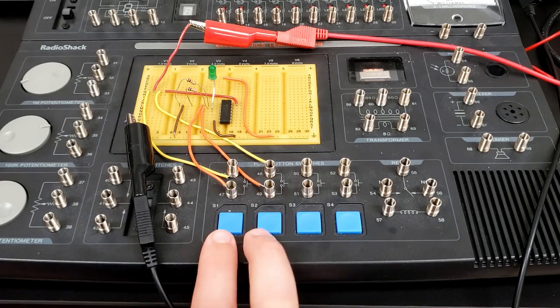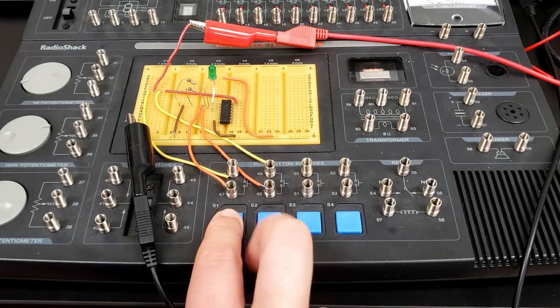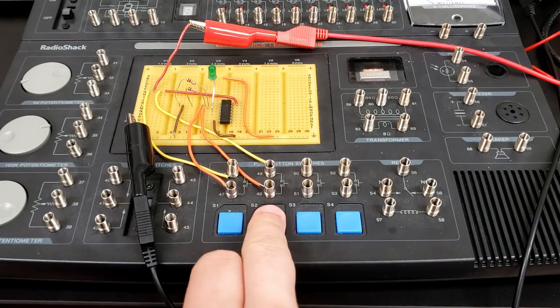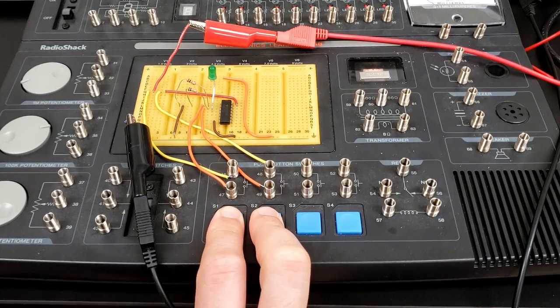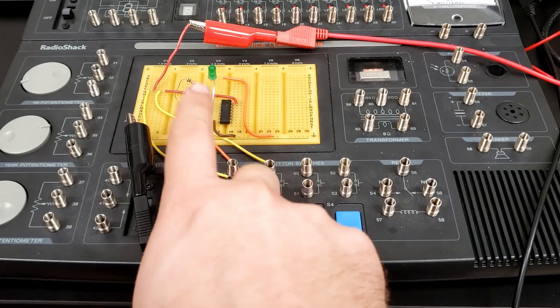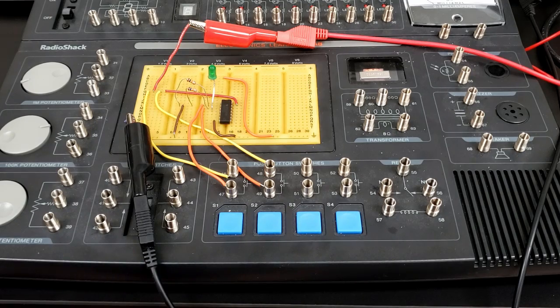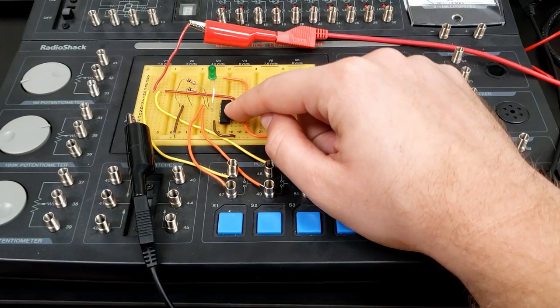Okay, so you can use that now. So it's on unless I press both of them at the same time, right? So it's still on. If I press S1, it's still on. If I press S2, only whenever I press both of them does the light go off. So it has an output of 1 unless both of our inputs are 1, in which case our output is 0. So you can now use that information to then find out what type of gate the 4011 integrated circuit is.